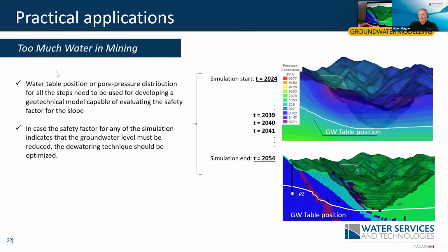Also, the model was used to calculate not only the groundwater levels to keep the pit dry, but also the pore pressure. In this case, FEFLOW provides directly the pore pressure, which was used as an input to a geotechnical model in order to guarantee slope stability.